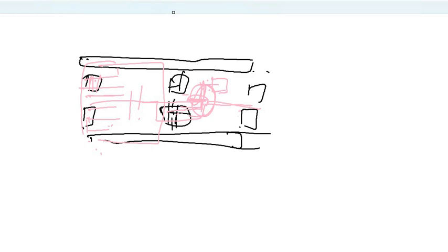On the other hand, it will also reduce capacitance. If you have all the metals going in one direction, it will lead to a lot of coupling cap. If you have alternating metals like this, it will reduce a lot of routing cap as well. That's the reason we have this concept. Okay, so let's move to the next slide.